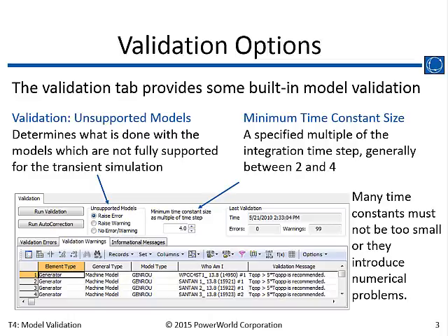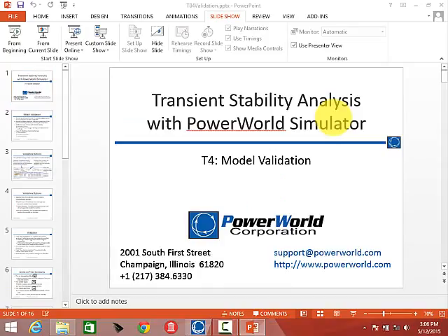If you would like, why don't you load in the WECC case and then load it in from the EPC and then go ahead and load the DYD. If you already had the case in there, you probably want to reload it because when you ran it, it auto-corrected the errors, and we kind of want to go through the errors right now.